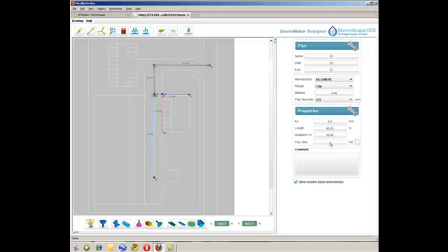The impermeable areas can be entered manually, having been measured on a plan, or by using the Select Area tool. This facility provides a quick and easy way of calculating an area directly off the working drawing by simply clicking around the area in question and right-clicking to finish the calculation. Once complete, the area is automatically entered in the data field for the pipe in question.